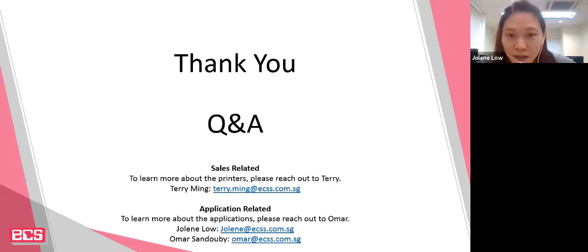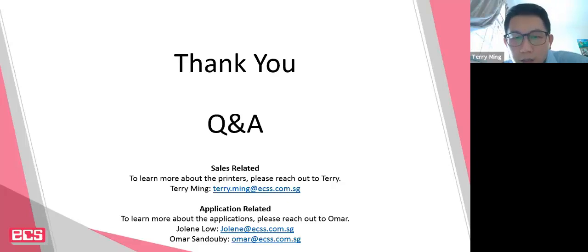In terms of support creation, it allows for optimizing print time and reducing support use. However, you have to take into consideration the functionality of the parts, like for example the screw thread case study that I showed. So in terms of functionality, you have to relook at the support and modify it from there. I hope that answered.